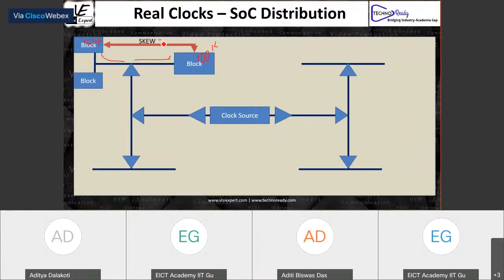So the skew is equal to 0 up to these blocks. Now, if there is a timing arc from this block to this block, would you still maintain a symmetric clock tree distribution up till all these 100K flip-flops? So will you keep doing this H tree up till all those flip-flops? Or will you just short multiple of them at some point of time using a single buffer? You'll lose the symmetry at some point of time.